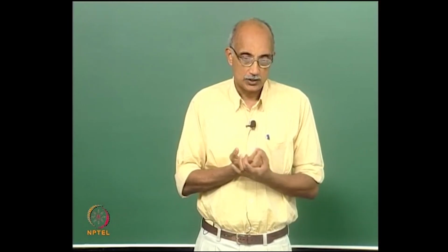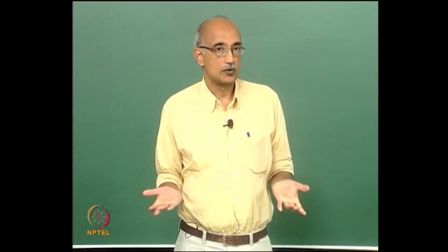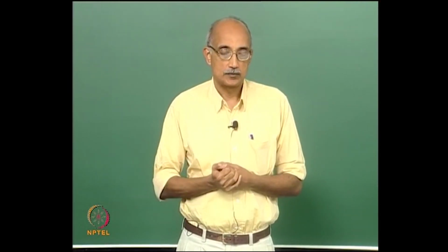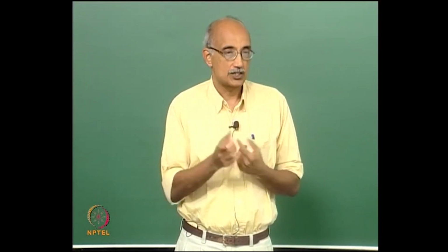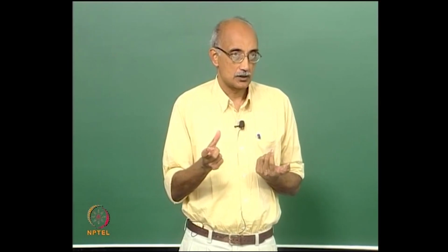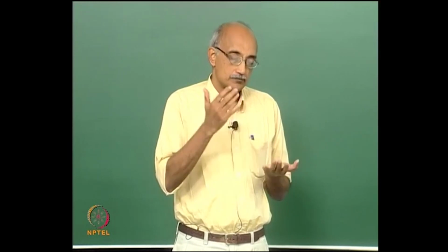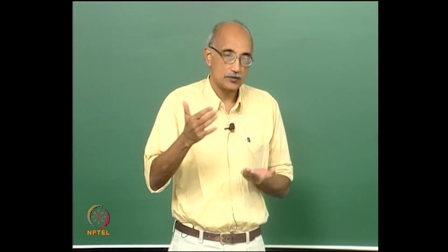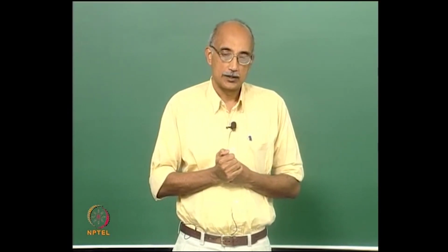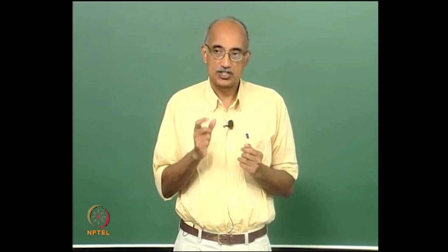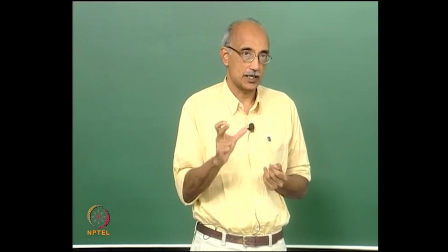Actually, some of the definitions that we used during our shape characterization discussion are obviously relevant for size characterization as well. Just to take an example, the distance between tangents, or parallel surfaces that are tangential to the profile of a particle, that we used as a measure of shape. But when you actually think about it, it's also a dimension that's a measure of size.